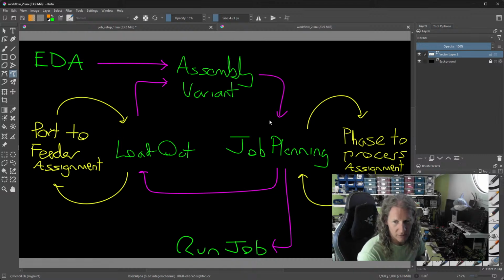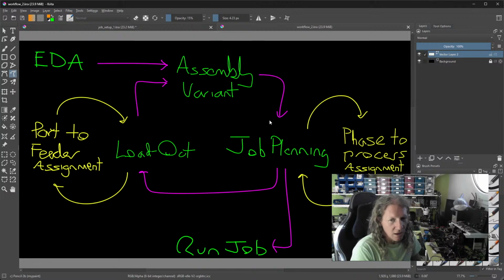So in the case where you've got a mixed technology board with through-hole components as well as SMT, surface mount components, you still want all of the parts listed in your parts database system. You need to know when you've used all the parts, you need to have all the stock counts updated, and some of the parts need to get placed by a machine, some placed manually by hand, right? And then you need to feed back into the system that you've done a particular job.